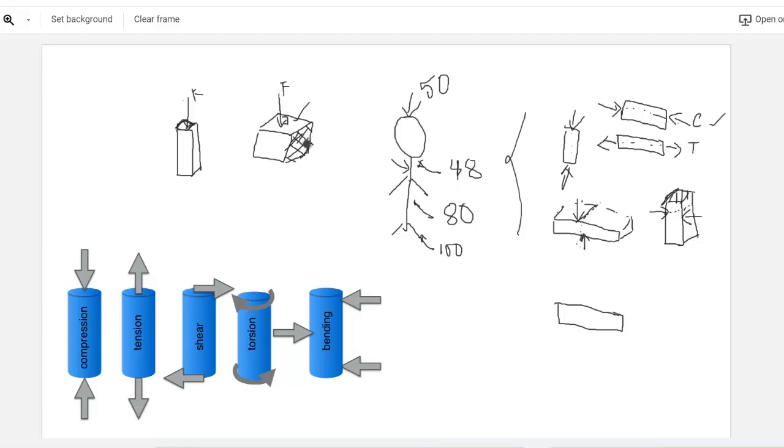So if you are considering the section, if I name it section V, this is with respect to this plane or this cross section, this F is the shear force. If you consider this one, this plane or this area, that time this force would be axial force. Now is it clear to you?